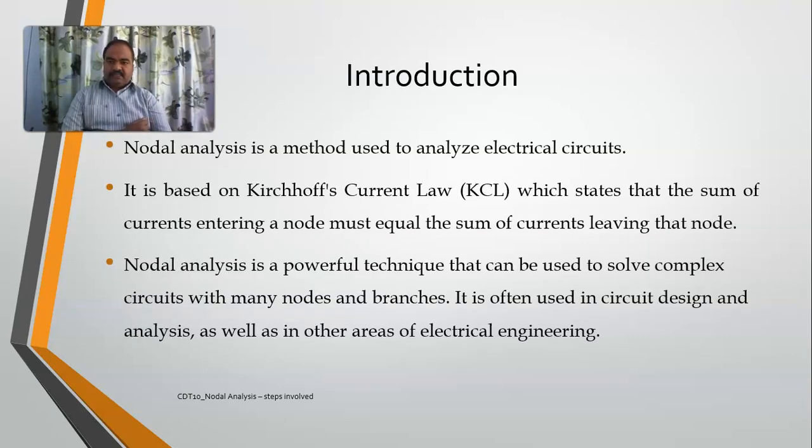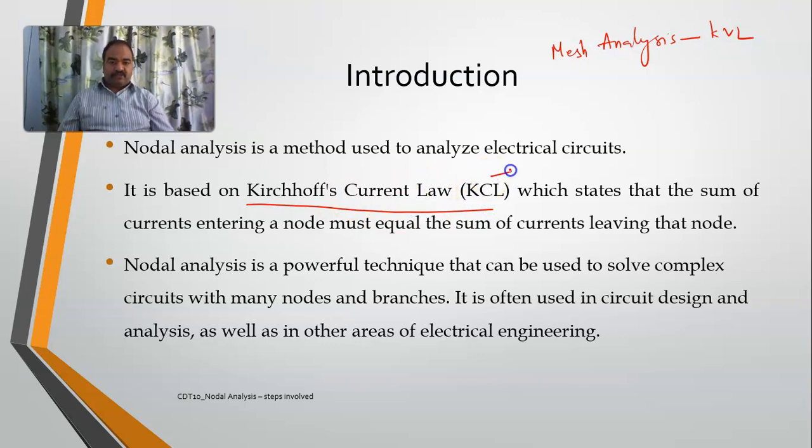Just like mesh analysis, nodal analysis is also used to analyze electrical circuits. Your mesh analysis was dependent on KVL, Kirchhoff's voltage law, whereas nodal analysis is based on Kirchhoff's current law. You know that sigma I is equal to 0 at any node in a circuit. It states that the sum of currents entering a node must be equal to the sum of currents leaving that node, or the algebraic sum of the currents at any node in an electrical circuit is 0.